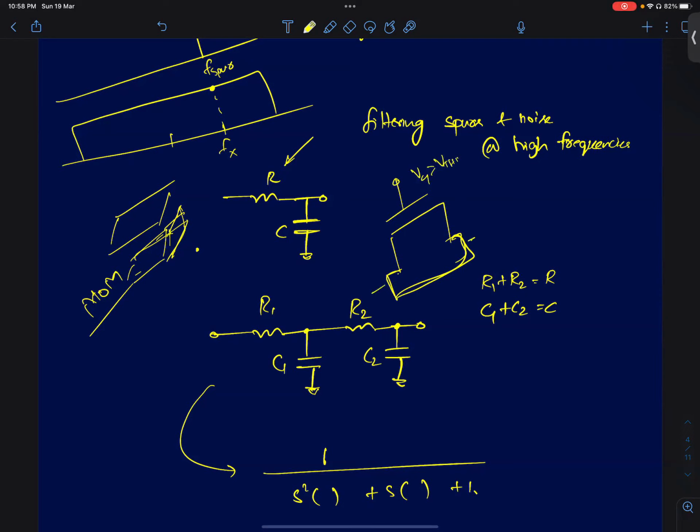Then the channel becomes conducting and behaves like a parallel plate capacitor. The gate is one plate, and the channel, drain to source, is the other plate. The oxide between the gate and the semiconductor acts like the insulator between the two plates. That is another way of realizing capacitors.